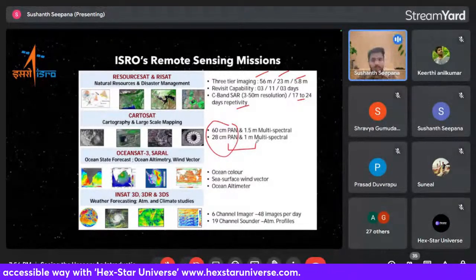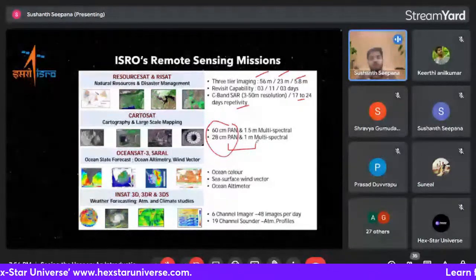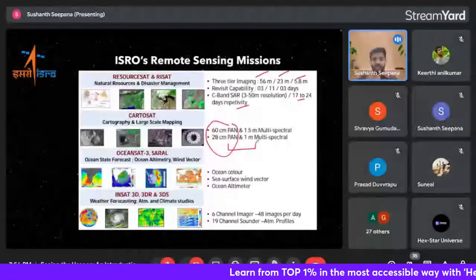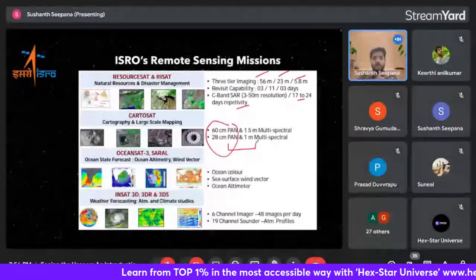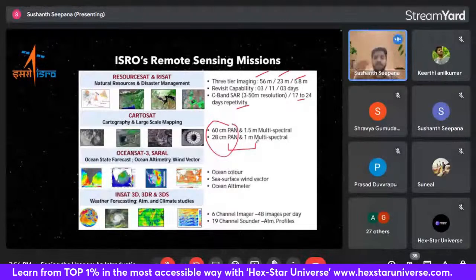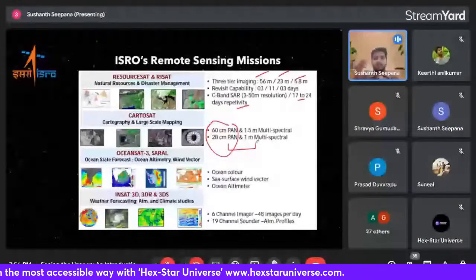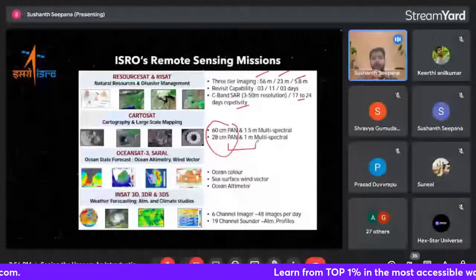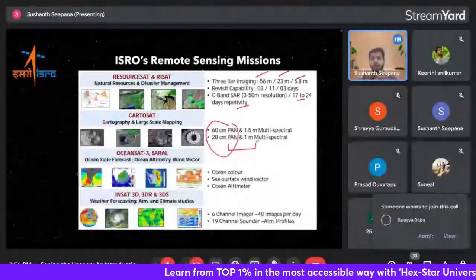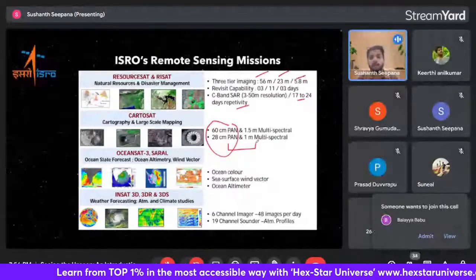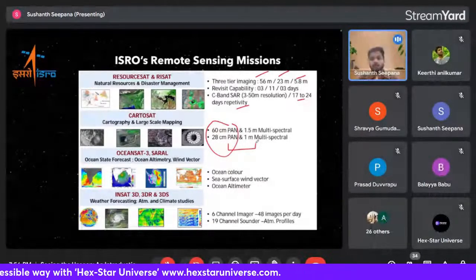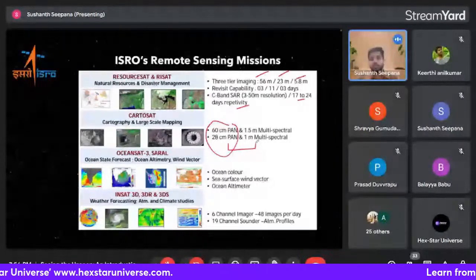But when you split it into only the red band, you can't get enough information from 30 centimeters. So you have to increase the spatial resolution to get strong reflected radiation. Since the satellites are at hundreds of kilometers, the radiation has to travel there, and while traveling, there is a lot of interaction with the atmosphere. So the spatial resolution and the spectral resolution are somehow indirectly linked. This is how we can relate them. This is about Cartosat, and there is one more satellite.